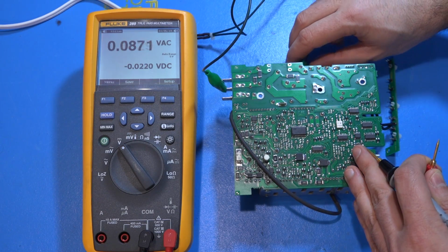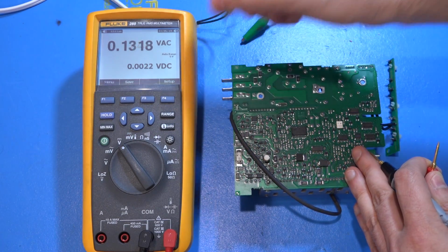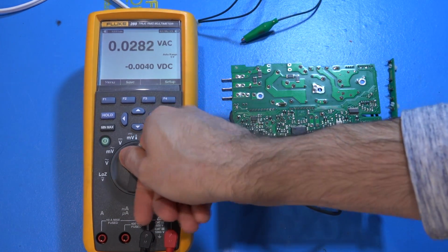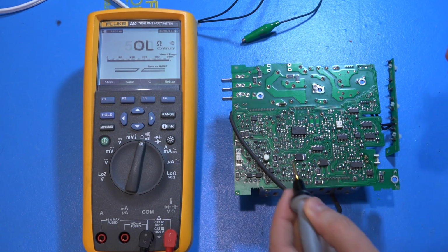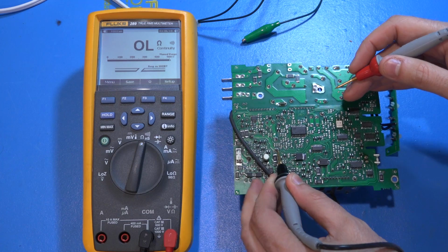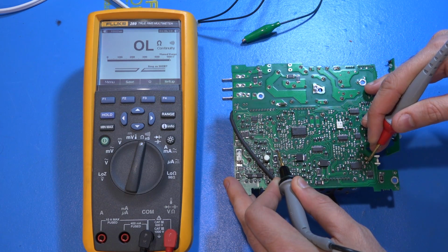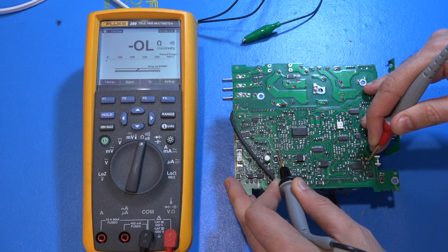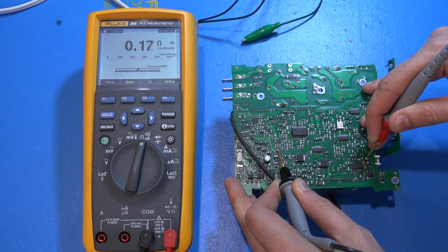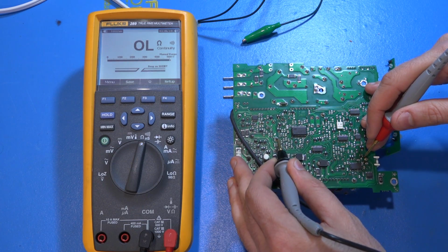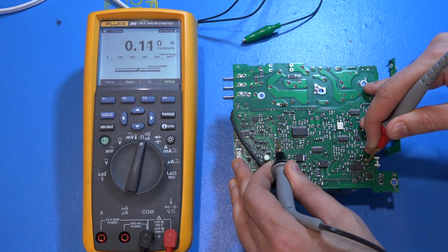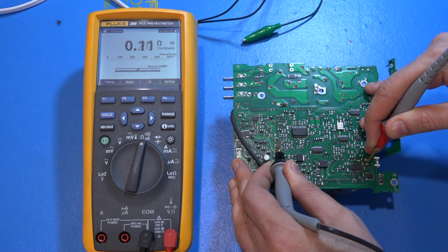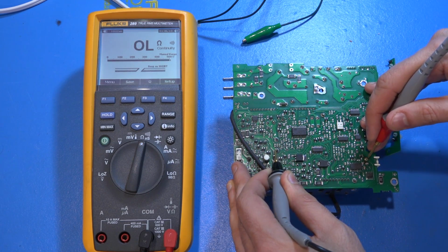We can verify by disconnecting this completely, get rid of this, and we can go ahead and measure resistance, so we can see continuity. I'm going to touch one side of this capacitor and go to the transformer. You can see I have a complete short circuit to both sides, and if I go to the other one, I see a complete short circuit on one side, and on the other side there is a complete short circuit. So these two are completely connected, and the other two are completely connected.